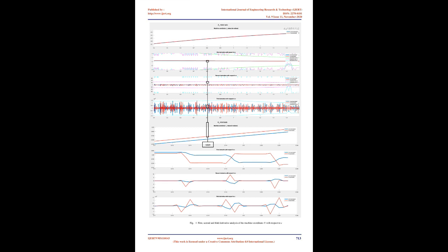Starting from 297 vectors of machine coordinates given with the appropriate G-code, the total vector displacement of the robot axes is calculated using the Euclidean metric in 6D machine space. The total axis vector displacement s is uniformly divided into 2,900 parts, and for every appropriate value of s, interpolated values of each machine coordinate are obtained by linear interpolation.